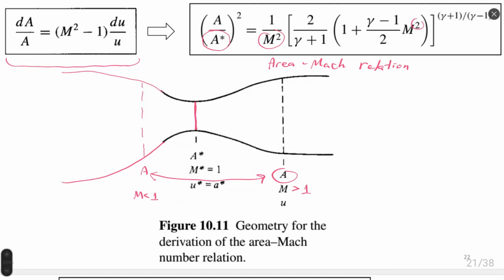So the equation of flow in the nozzle gives us the possibility to solve flow properties for accelerating flows in the subsonic section and for decelerating flows in a supersonic section. Such an equation is based on the isentropic model. So the flow is isentropic, with constant entropy, with constant stagnation pressure and constant stagnation temperature as well.